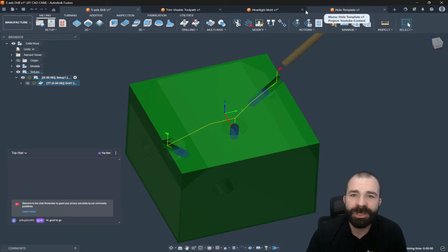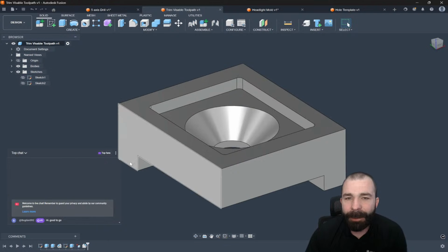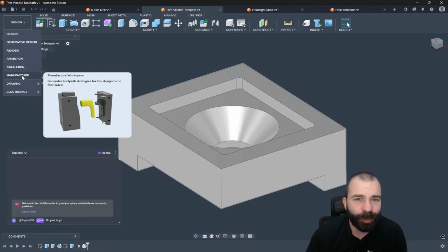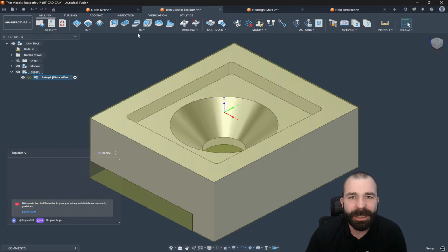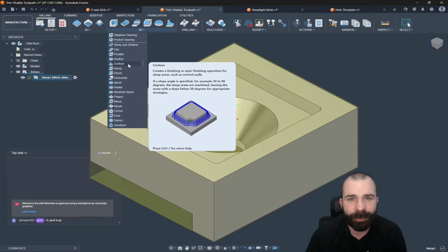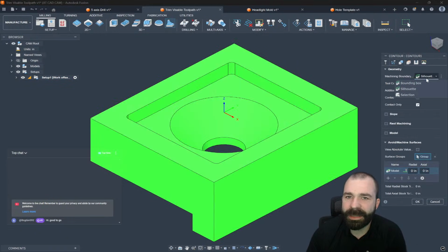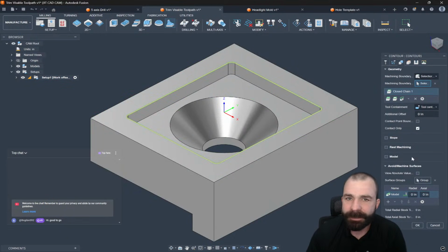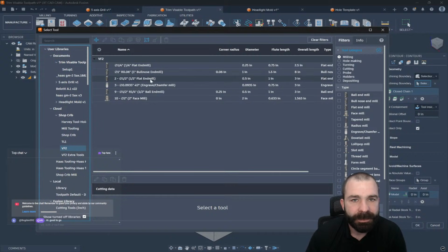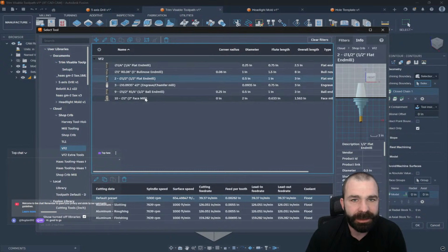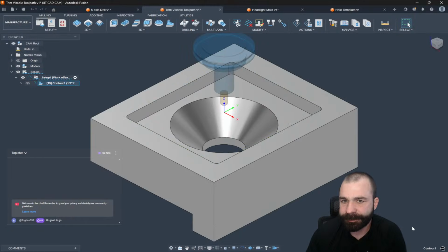So let's go ahead and shift gears a little bit. I'm going to show you guys this neat little thing inside of Trim Toolpath. If you're like myself, we go in, we create our setup, and then I'm going to do a 3D contour on my part, right? Let's say I want to stay inside of my boundary, and then from that, we're just going to let this toolpath do what it naturally does. Again, let's just get that 1/2-inch ball inside of here. There's a 1/2-inch ball end mill.